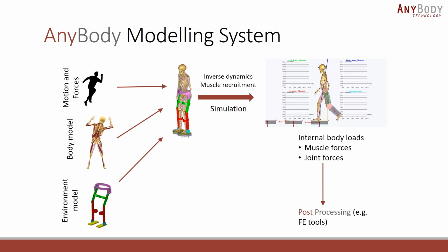So in case these loads form your final output, you can go ahead and pass this data on to certain post-processing tools such as finite element models. And there are certain interfaces, or certain tools, to actually interface the results from AnyBody with some of these finite element software. Or in case you are interested in the optimization of your environment, so as to induce a certain desirable effect in the human musculoskeletal system.